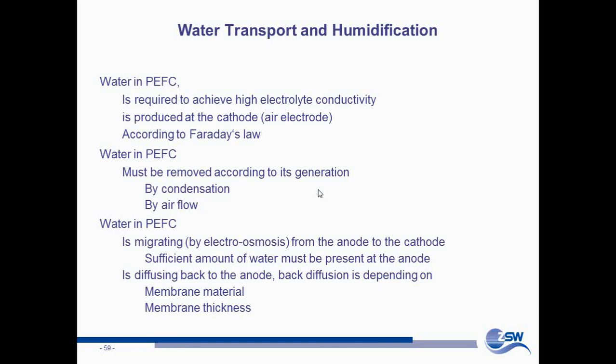Setting the right or wrong operating conditions will push water removal to either the anode or the cathode side, right? Operating conditions and material selection are the key to where you find most of your water removal. And most of the operating problems in PEM fuel cells are unwanted water at the anode side, flooding of the anode.